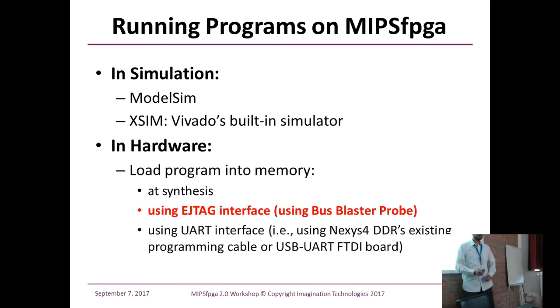So there are many ways to run programs on the MIPSfpga platform. Each way is kind of tailored for different labs and environments. Not all labs can go and buy all the hardware. Some have different FPGA kits. Some want to run simulation only. So you can use ModelSim or XSim in Vivado. It's well documented in the teaching packages.